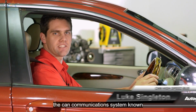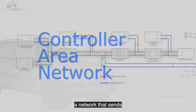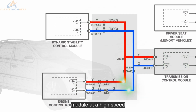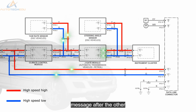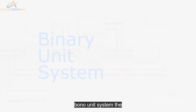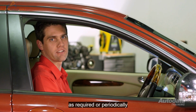The CAN communication system, known as Controller Area Network, is a network that sends and receives information between control units. Transfer occurs between each module at a high speed and are sent serially one message after the other. The most common name for this system is a bus, binary unit system. The information can be transferred as required or periodically.